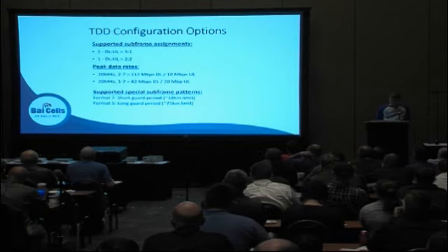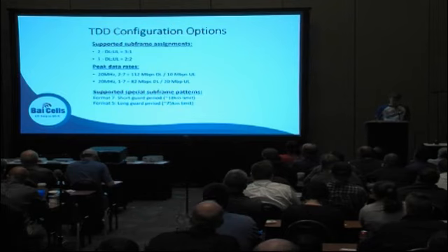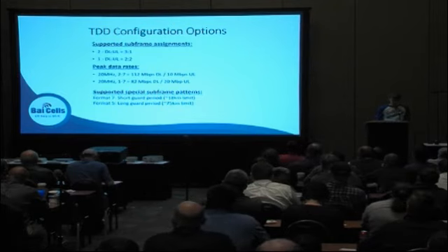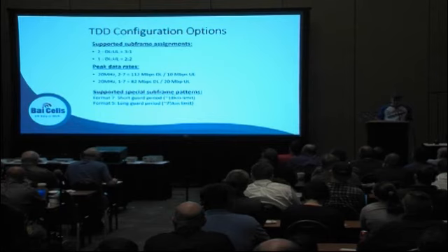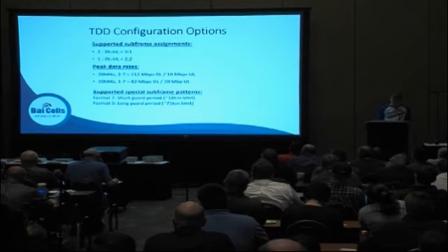So the aggregate throughput of the base station could theoretically go up to 112 downlink in the default config. If you change that to 1, the downlink drops, but you do double your uplink performance. And I also wrote the cell radius depending on if you set the special subframe to 7 or 5.